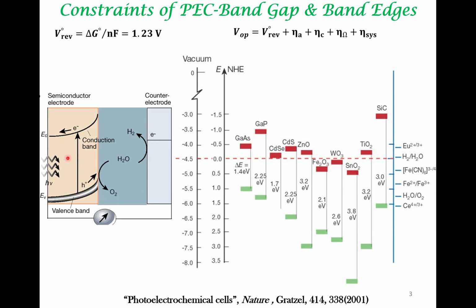It is also that when silicon is exposed to an electrolyte atmosphere, the surface gets oxidized and forms silica at the surface, which is a very insulating layer. So both reasons contribute to not using silicon, at least just a plain single junction silicon. But silicon can be used in other ways in the system, but we are not going to that.